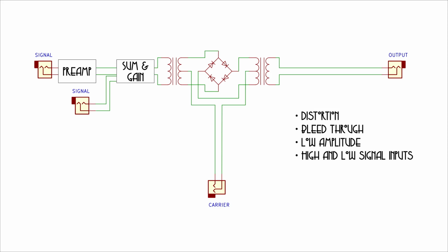There's one that just goes directly into a gain stage, and there's another that first goes through a preamplifier. You use the first of those if you want to use a synthesizer signal. Use the second one if you want some sort of external signal, like if you want to run a guitar through a ring modulator. You put it in this low-level input, and it goes through the preamp. So you've got some additional flexibility there.